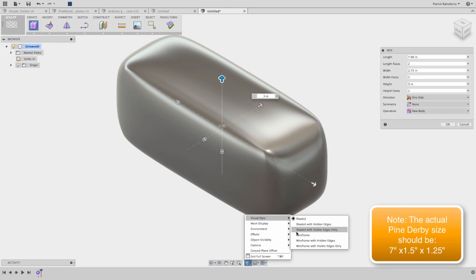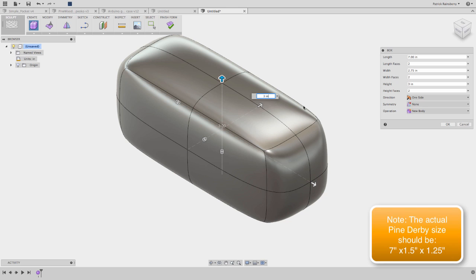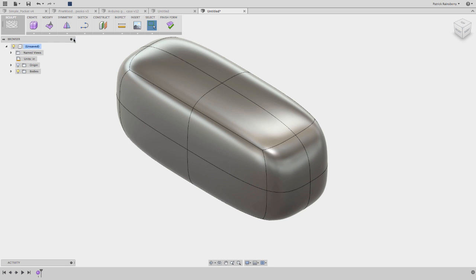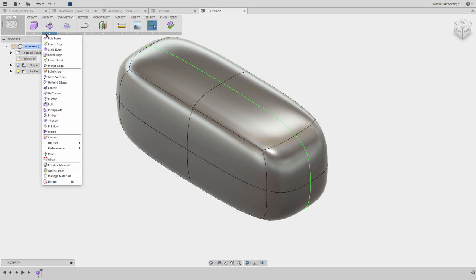And now this is based on what we call T-splines, and you'll see now if I turn on shaded edges, you can see essentially the patches that make up this surface, which is a little different if you've used other surface modeling. This is like T-splines based. So I have a lot more power here. I can do, right now I'm going to show symmetry. So to define symmetry, you just click on two opposing faces and you'll see that green line represents symmetry in this model.